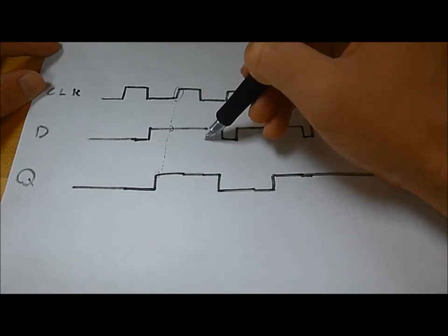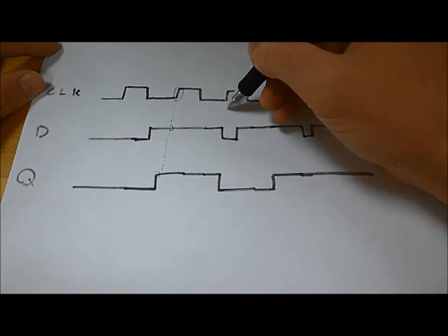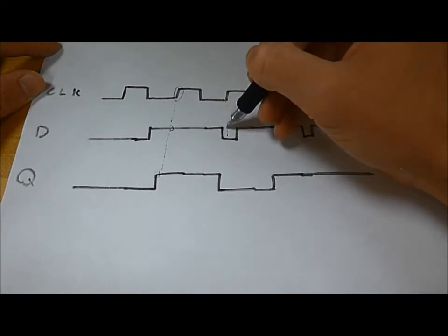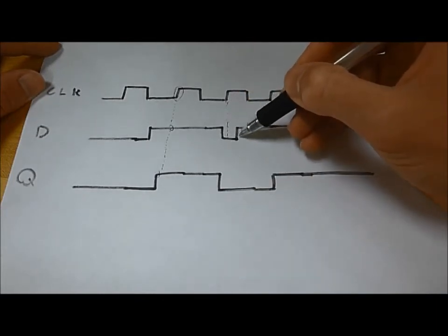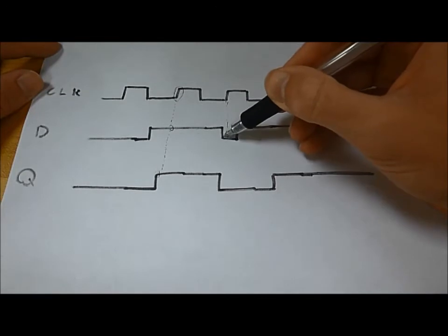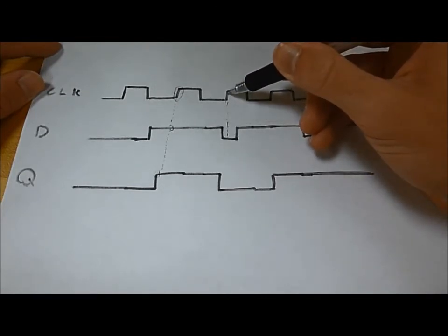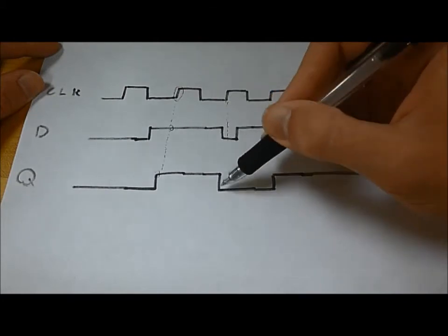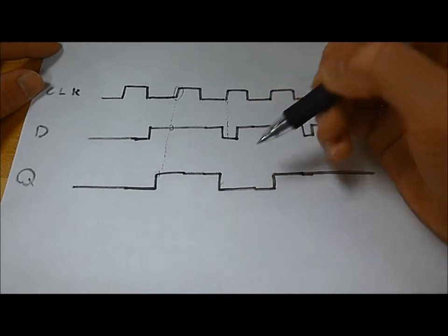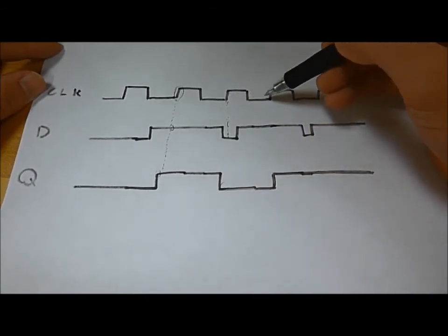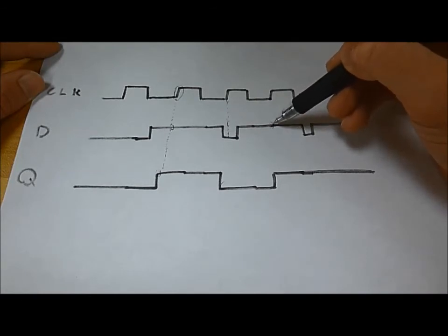Even if D had fallen to 0, we don't mind. This positive edge, Q goes to 0 because D is now 0. You'll notice that D can change very quickly, but as long as it's low or stable, when the clock signal goes high, that value will be, quote, clocked in to our Q. So, if we go through here, we can see, again, rising edge, and we have a 1.